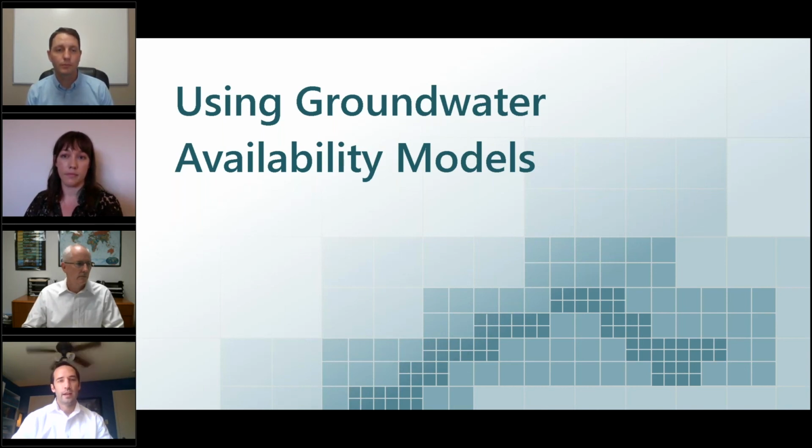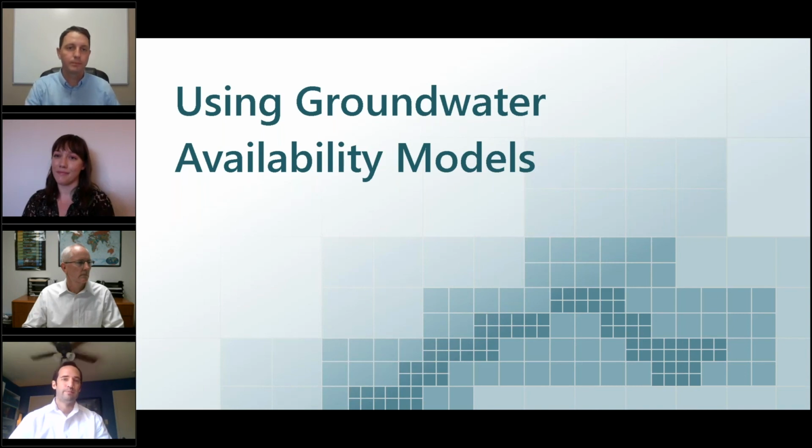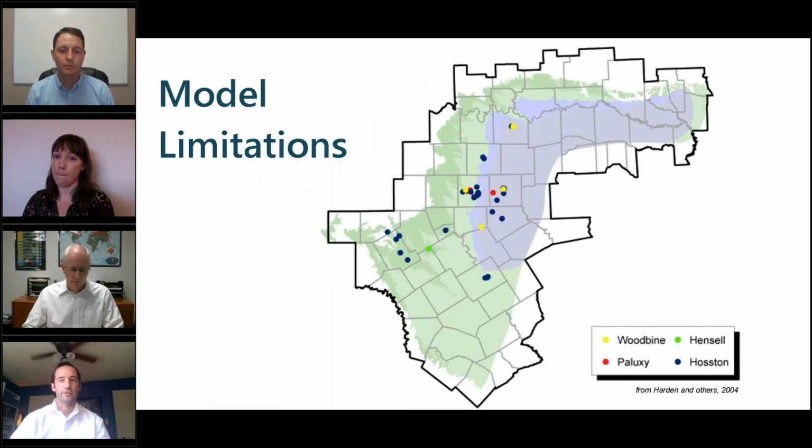Sure. So with that, I think we're heading towards a discussion of boundary conditions, is what I'm hearing you say there. The boundary conditions in the model determine where water enters and leaves the model, of course, right? And you have everything from lakes, streams, recharge, the ET package, and wells. And as Andy mentioned before, you have the three different types of boundaries: specified head, specified flux, and head-dependent flux. So you have to think carefully about those boundaries that you choose in your model, because they obviously have a large impact on your results, as both Andy and Natalie mentioned.